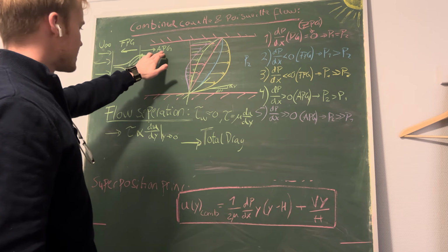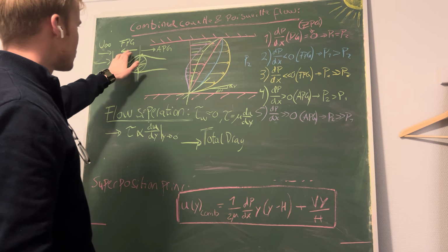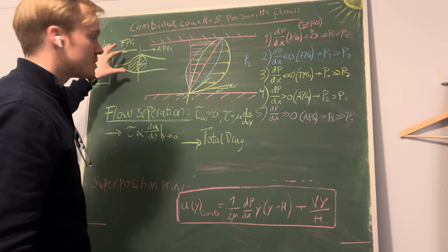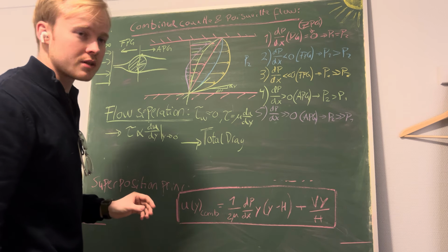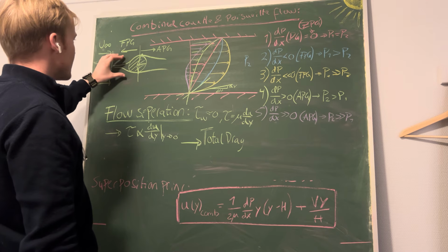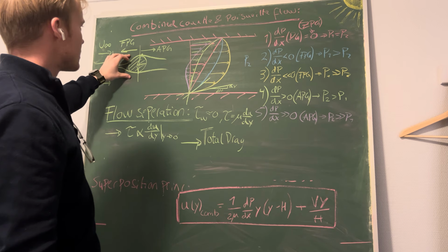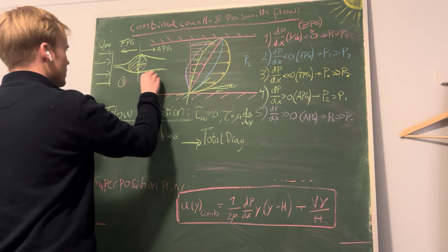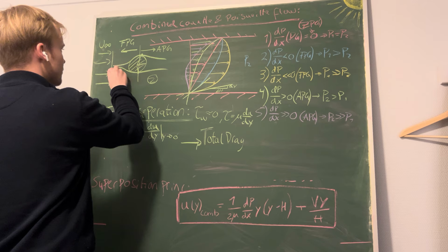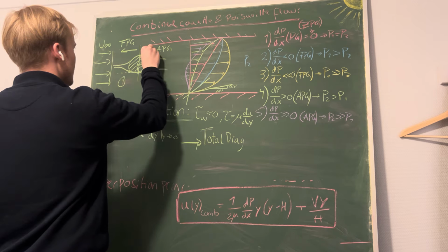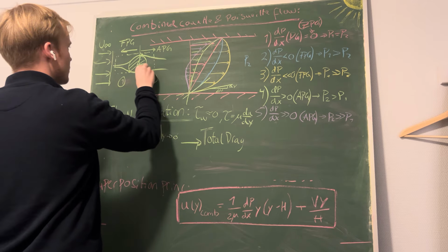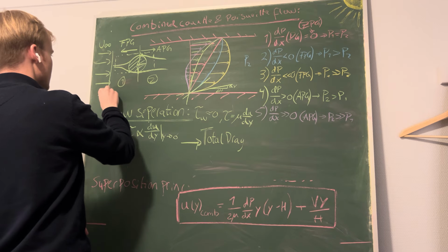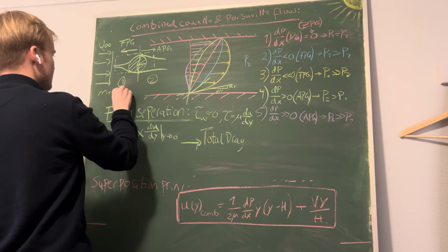What you could basically say here is that a favorable pressure gradient is when the streamlines are squeezed together, which means that the flow is accelerating. That is because if we use continuity, at our area 1 and then at our area 2, if we set up a small control volume around this cylinder, mass flow 1 should be mass flow 2.